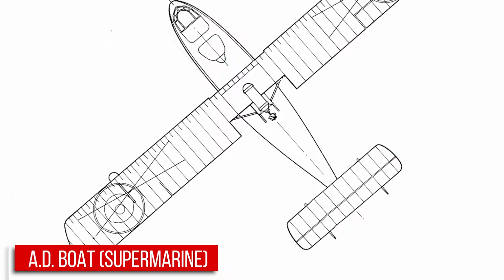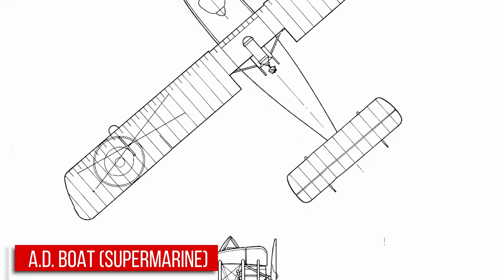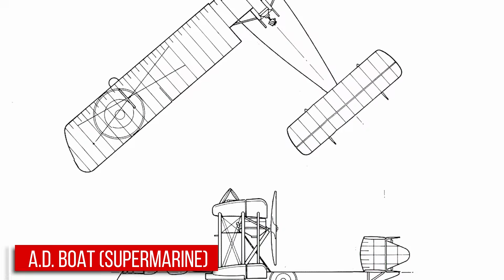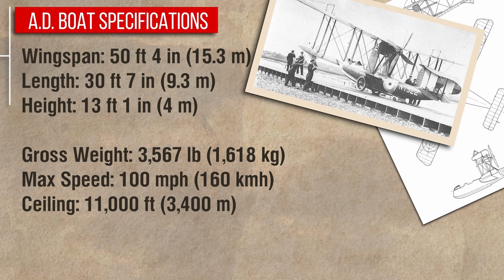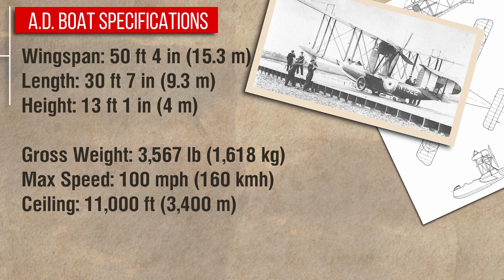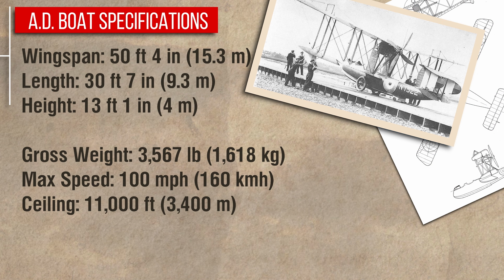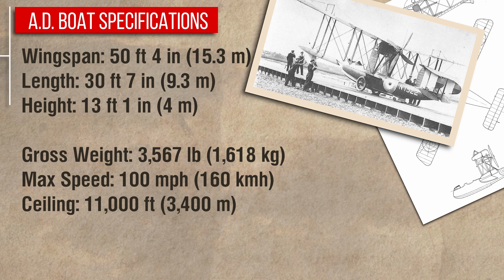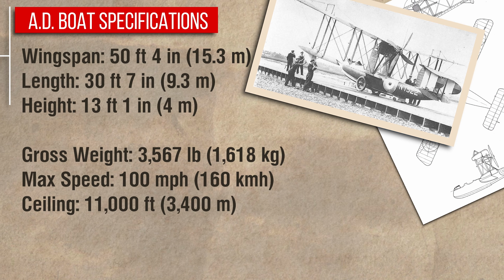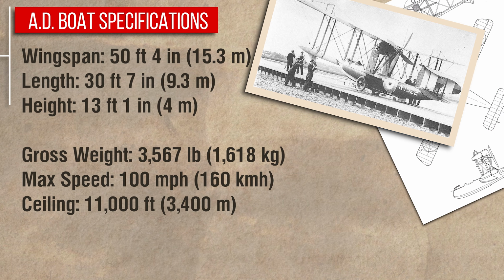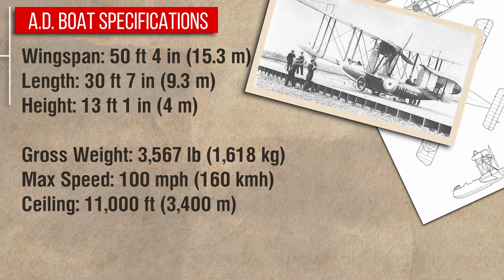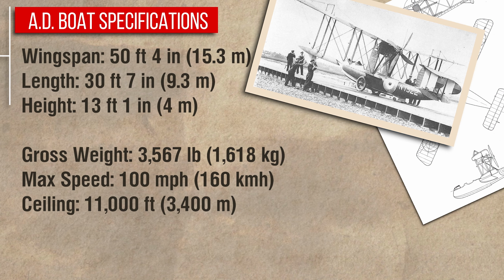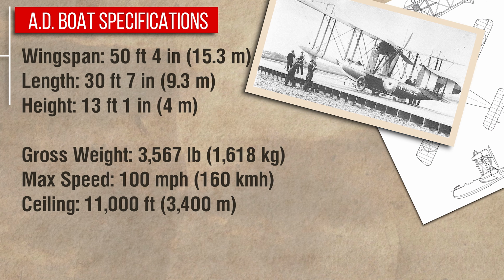Like many of the earliest flying boats, and these were among the first, they were plagued with hydrodynamic problems. It suffered from chronic porpoising on takeoff, and it had some truly alarming yaw defects. To get up safely, it had to be initially pointed downwind, and then as the speed rose, it had to be gradually turned into the wind. This turned out to be the result of the rudder and fins being too small, which meant that control at slow speeds pointing into the wind was presumptively optimistic.